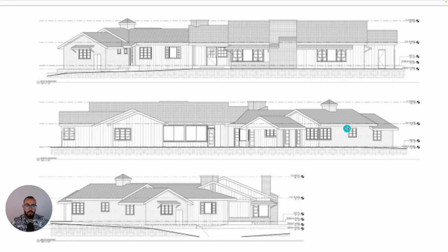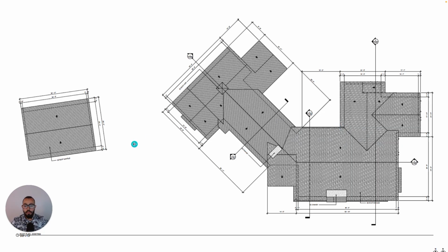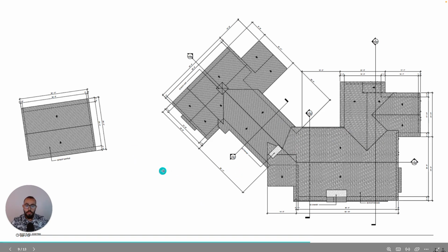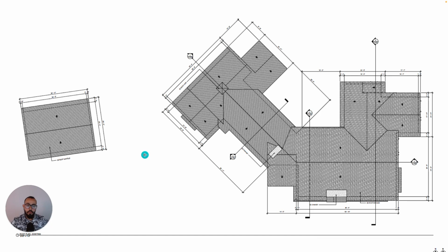The next one, the last one I want to show you for this video, is another type of as-built drawing. This one is a roof plan. So a roof plan represents the building when we look at it from the very top, and this is something that is needed, like I mentioned, for other design and building professionals. Let me activate the drawing command. So this will show the direction of the slope of the roof and the outline of the building below it,